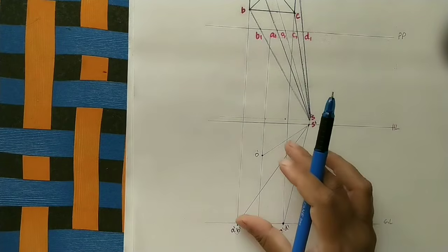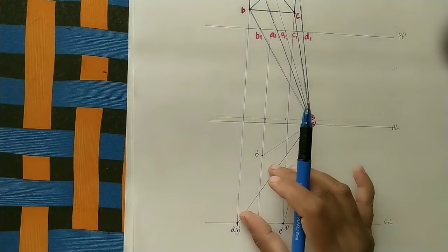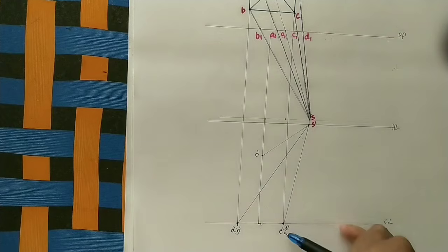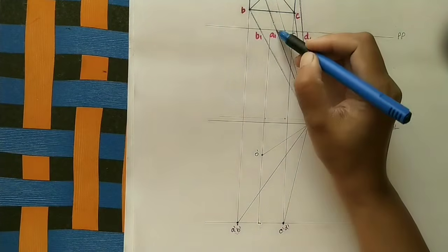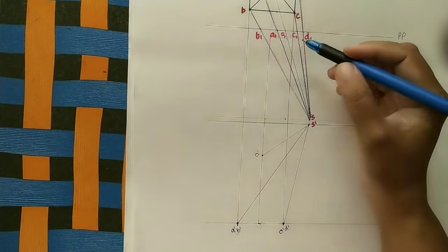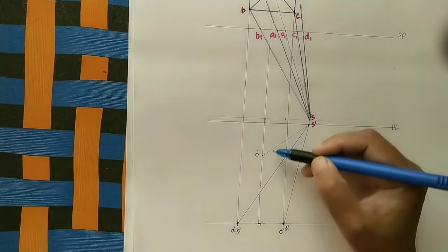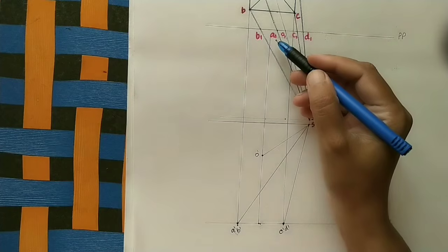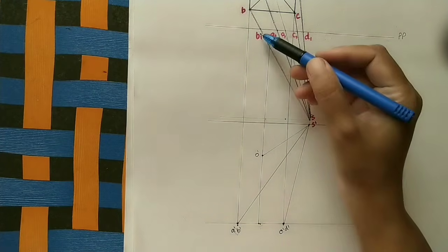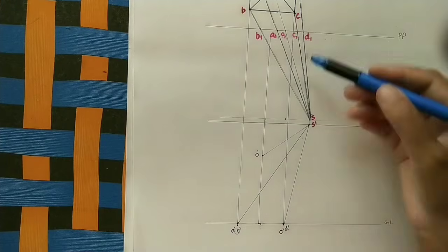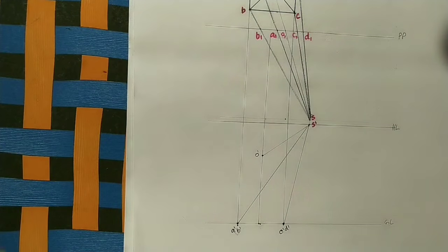Now our main aim is to do the perspective view. Initially we will do the perspective view, after that we will do the side view by joining this. For doing the perspective view, wherever intersection points are there, from A1, B1, C1, D1 like that, just do the projector line from A1 up to the A inclined line. From A inclined line here to A inclined line this side. Similarly from B to B inclined line, from C to C, D to D like that. We will get the vertical projector lines.